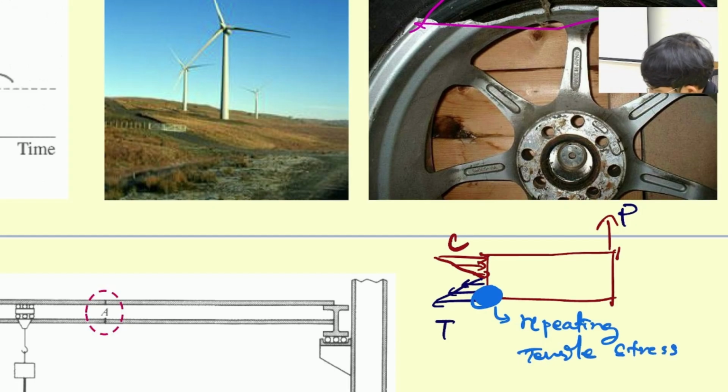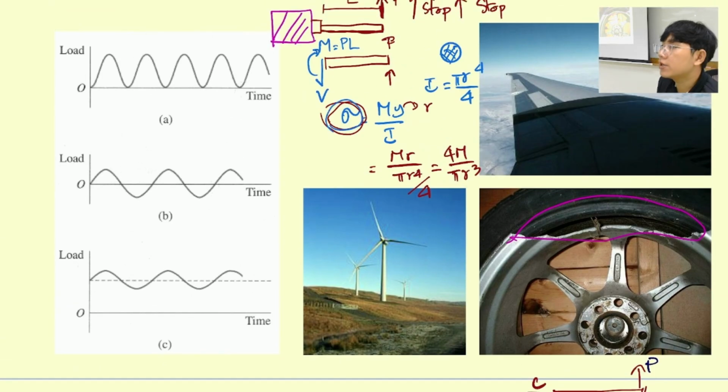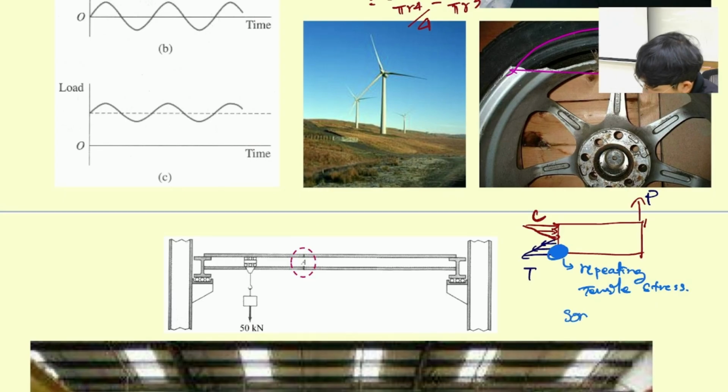stress, which means the material does not need to fail by pressing it until it fails. Sometimes if you apply only 50% of the sigma over here, the stress over here, but you apply it and then you stop, you apply it and you stop in cycles, which means loading, unloading, loading, unloading, at some cycle the material is going to fail.